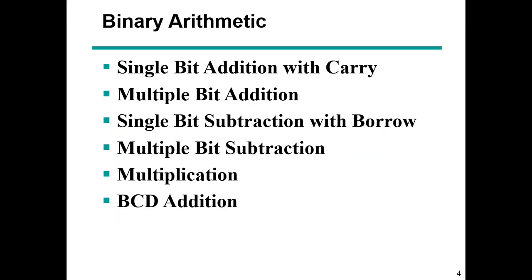In digital systems, we basically implement an operation for a single bit, and then we create a digital logic block that can carry out a single bit operation. And when we want to carry out multiple bit operations, we employ multiples of those blocks and put them in a cascade so that they can do multiple bit operations, whether it is addition, subtraction, multiplication or any other thing.